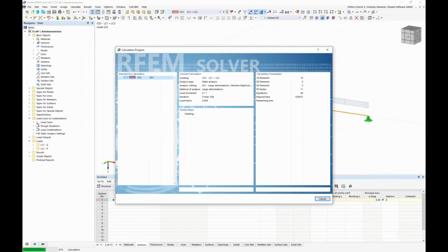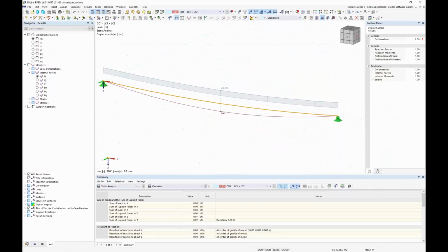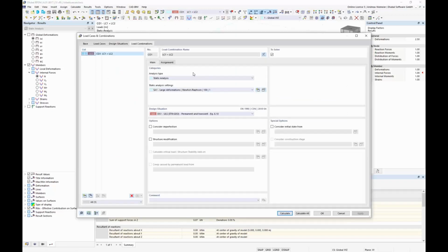and after confirmation and rerun we will get the 20 centimeters hopefully, and yes, we get it. So you see the program searched for us the shape with 20 centimeters with a corresponding force of 0.4 kilonewton. So far this was our first form finding job in RFEM 6. And maybe you saw now that we gave you as users a new mighty power in the program to work with shapes.